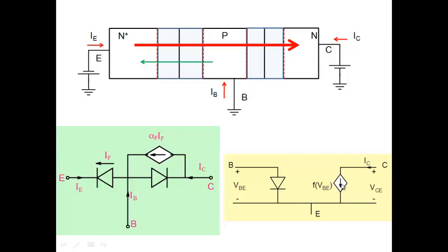So that's where the transistor action is. I have a current flowing between these two terminals, which is very sensitive to the voltage applied here, but is not sensitive to the voltage applied here. And that's what we were looking for. In an ideal transistor, we had shown this as an open circuit, and we had shown that the current varies linearly with the voltage here. In our case, the current doesn't vary linearly with base emitter voltage; it varies exponentially. But it shows the basic feature of current being very sensitive to the voltage here and not sensitive to the applied voltage here. So that's where the transistor action takes place.